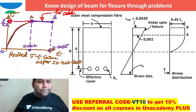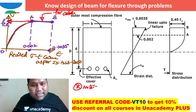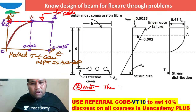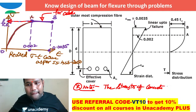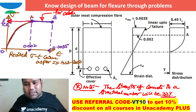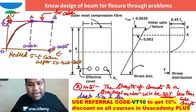I just want to write a note: the strength of concrete in a structural member will be less than the strength of concrete of a cube, right? The strength of concrete in a structural member will be 33 percentage less, due to size and slenderness effect.